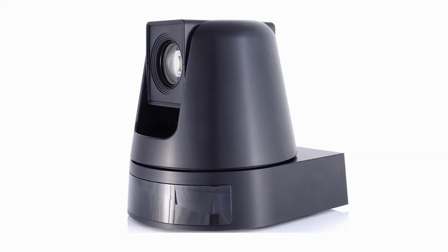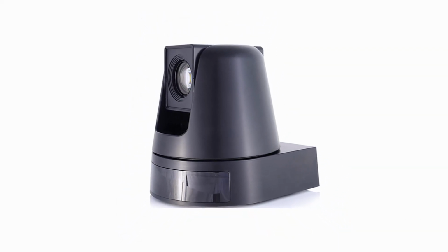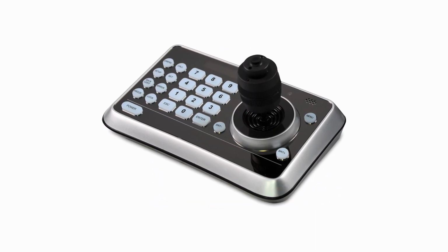So you have a mixer. Now you pick out your cameras. If you have pan, tilt, and zoom cameras, PTZ cameras, most of those can be hooked together. You have one remote that can control those from a distance. When it comes to a manual camera, just make sure every camera can handle the exact same resolution across the board, as well as your video mixer. Now this makes this really easy, because if you're not retrofitting this system and you're building it from the ground up, just get the exact same camera across the board.